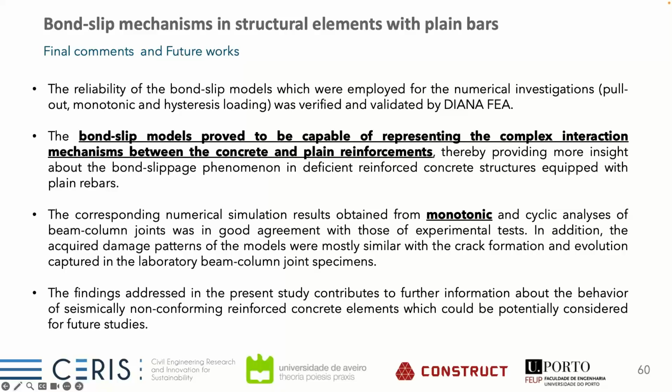And we want, of course, to keep studying this, in particular in seismic non-conforming reinforced concrete frames. It's quite important to highlight, and I have not highlighted this in the beginning of my presentation, that to model this type of frames with this type of behavior, where the damage and the behavior is ruled by the joint panel, is quite hard with traditional nonlinear fiber approaches with concentrated or distributed plasticity. It's quite hard to capture this nonlinear behavior, so we need to use this type of more refined models if you want to study in more detail this type of frames. And that's why we are trying to use these models in our studies.